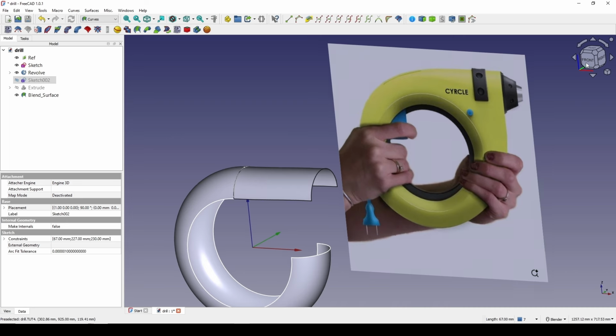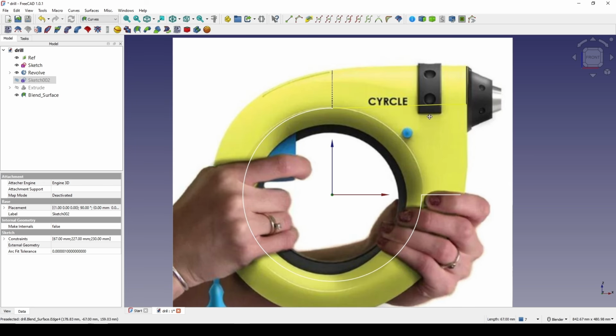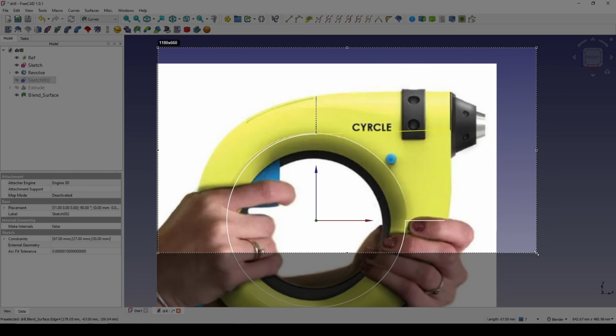And I go to the front view, and you can see if I show the wireframe, I have a sharp edge running somewhere in here to here, to touch on this point. So I need to cut the shoe, remove this geometry.